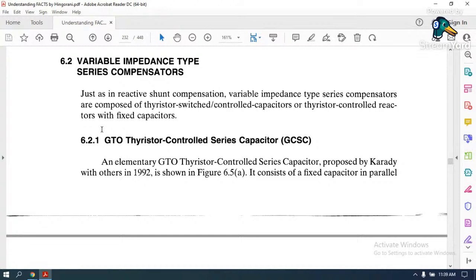From now on, whenever I say we are connecting a compensator, I am connecting one series capacitor into the transmission line, just to reduce the value of x. And you all know the degree of series compensation is given by xc upon x. Last lecture we saw that we replaced xc upon x by k. As you increase k, x decreases, and as x decreases, P increases.